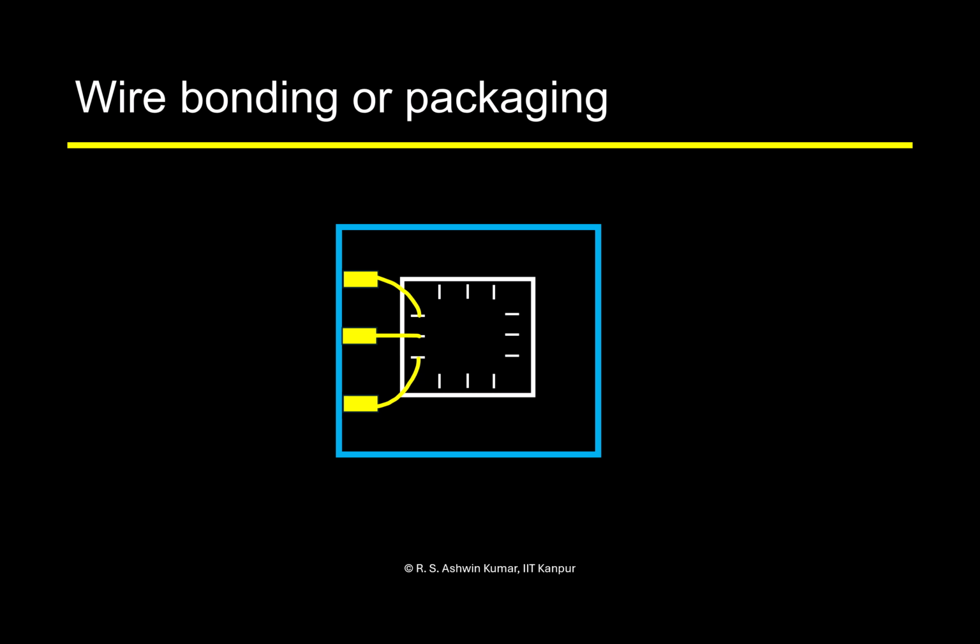But anyway, now we have a long wire like this, and because of gold, let us say the resistance is going to be small. So what will this wire contain? If you have a long piece of wire, is it a short circuit or something else? What is the simplest model? Resistance is small. Let's say we have a metal line like this. What will it have? It's an inductor. In practice, both R and L, but gold has really small resistivity, so that resistance is negligible. So it will be an inductor.